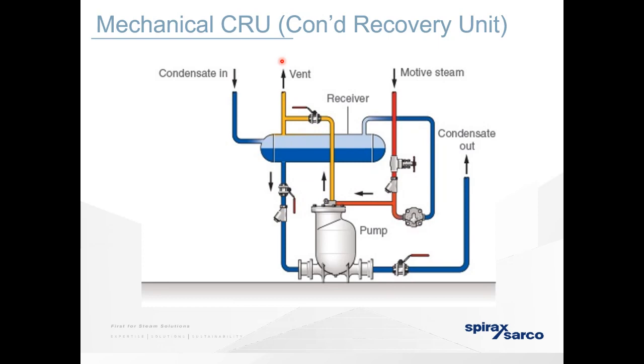Yes. The other question is about condensate recovery. Can we calculate using the condensate recovered volume and the steam generated volume? Any variance to the ppm approach? Yeah, you could. You get the value of how efficient your system is by seeing how much volume of condensate you've sent back versus how much steam you've produced.